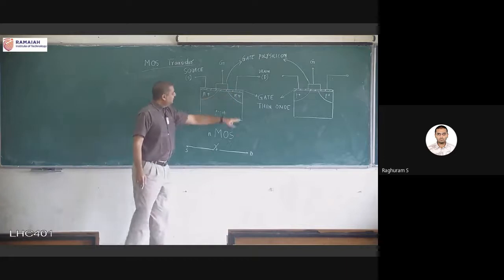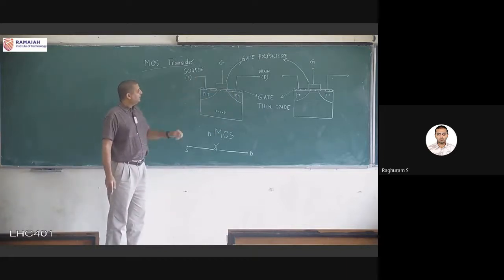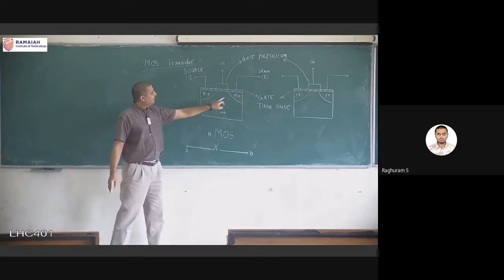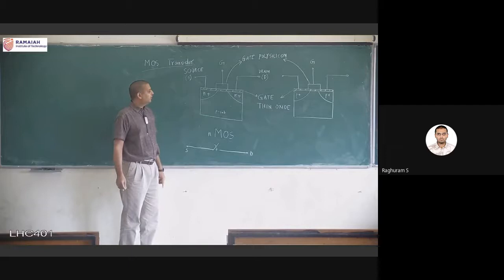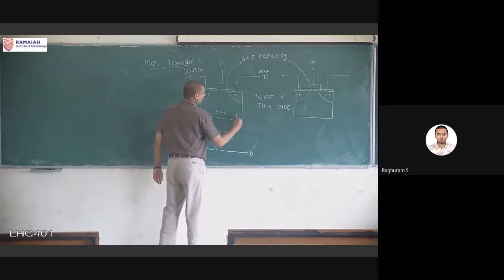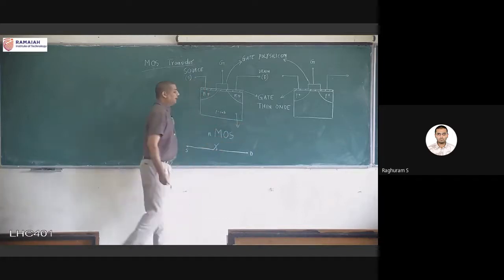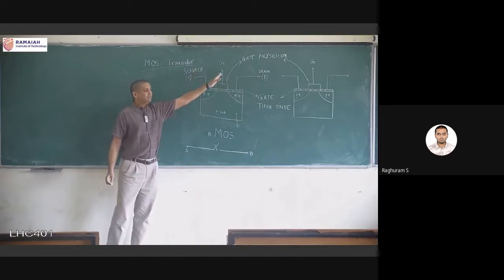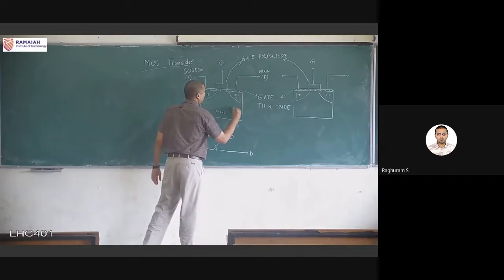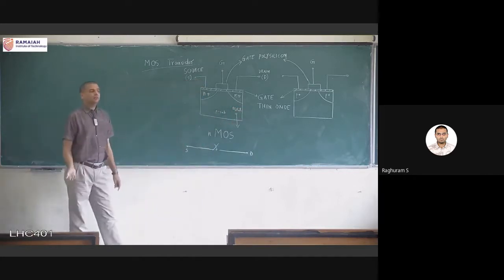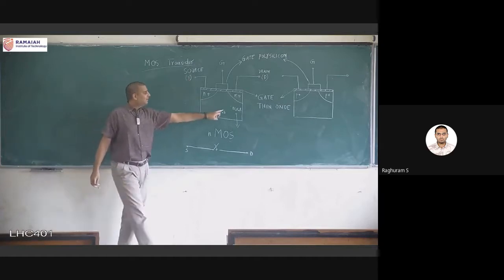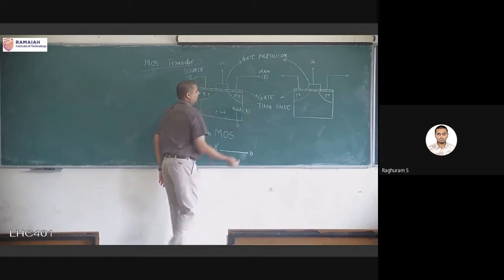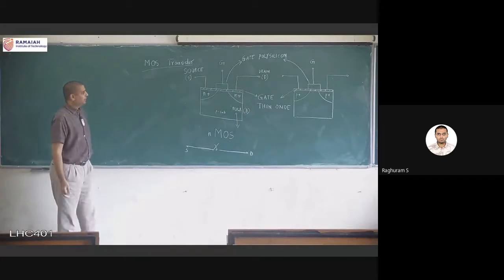So this is the structure, and if you remember, in an NMOS transistor, source and drain are of type N plus, and this should sit on a P type substrate, or it might be a P well, that depends on the fabrication. For now we will just assume that it's sitting on a P type substrate, no problem. Okay, and necessarily there is a fourth terminal, but generally we will not control this terminal. That is, this is the source, drain, gate, and the fourth terminal is called the bulk or substrate. It might be confusing to call it substrate, because already this is called S. So because of that it will be called the bulk terminal, with the letter B. So that is the fourth terminal called the bulk terminal. So these are the four terminals.